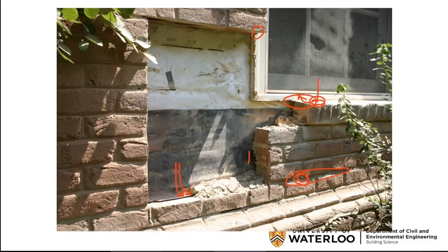But Max, the rubber flashing isn't lapped. Yeah, I think this flashing isn't lapped. The building paper, the house wrap, goes behind the rubber flashing. So I just saw the text there. It was there, but that's like tucking your pants into your boots when it's raining. Any water that runs down your waterproof pants is going to go right into your boots.